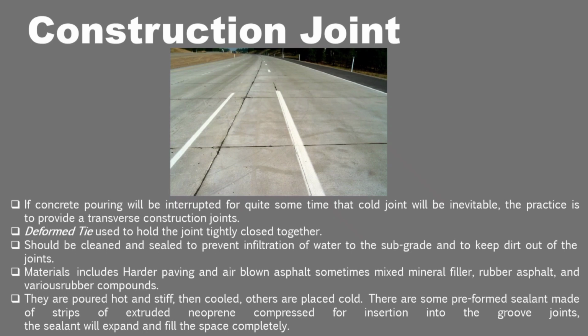And lastly is the construction joint. First, if concrete pouring will be interrupted for quite some time, that cold joint will be inevitable. The practice is to provide a transverse construction joint. Second, the form tie is used to hold the joint tightly close together. Third, it should be cleaned and sealed to prevent infiltration of water to the subgrade and to keep dirt out